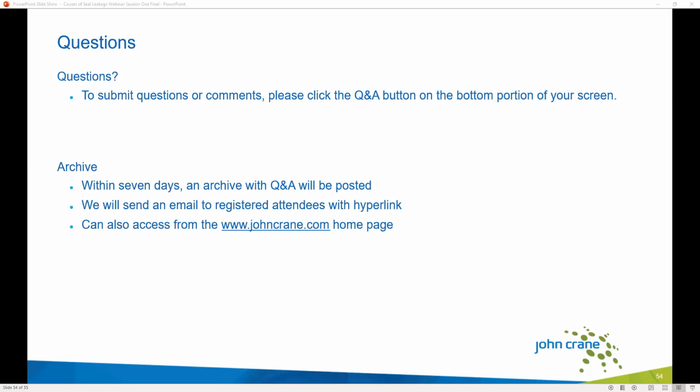So for example, if you're monitoring the pressure and temperature of the fluid within the equipment, if there's any deviation from what it's supposed to be, particularly higher pressures and temperatures, usually danger zones, then my recommendation would be to detect that and correct it before there's an issue with the mechanical seal.